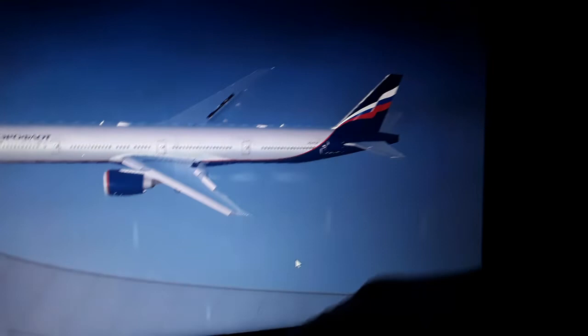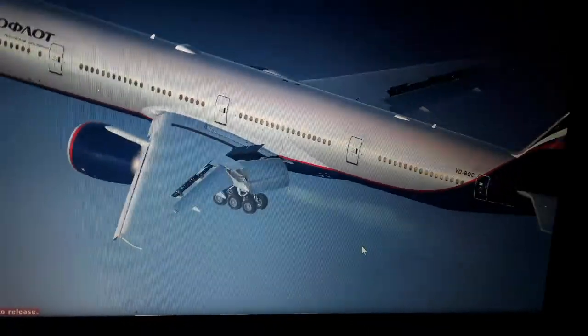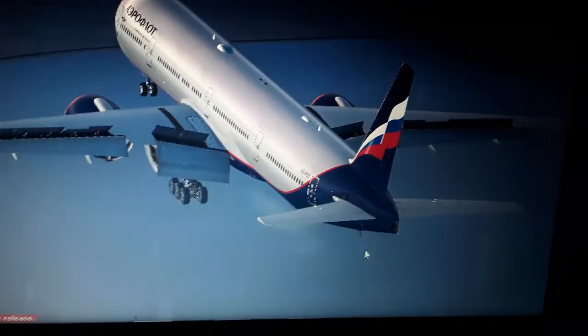I'm gonna talk to you about some physics now, some Newton physics and some mathematics. So this makes the aircraft have less wing loading and makes it easier. It makes the stall speed less, so you can fly with lesser speed or take off more easily using less runway. If we use the proportional flaps and flaps for takeoff, as you can see here, the flaps are expanded. The surface is over here.